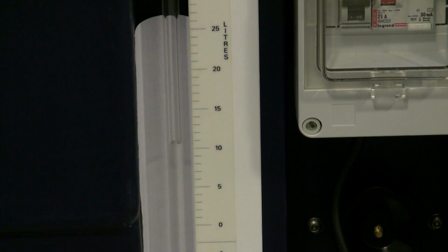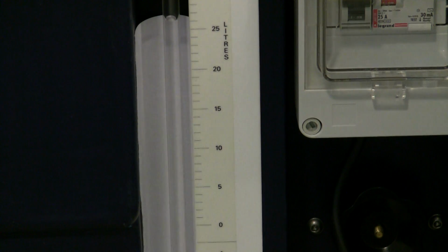Just based on human reflex, you should typically use times of 20 seconds or more. As long as you do that, then stopping it early or starting it early won't be too significant compared to the overall elapsed duration. It'll be a small fraction of it. So I'm going to do mine from 5 to 20, which means I had 15 liters. Okay. I'll leave it to going up to 25 for those of you who want all the way accuracy.